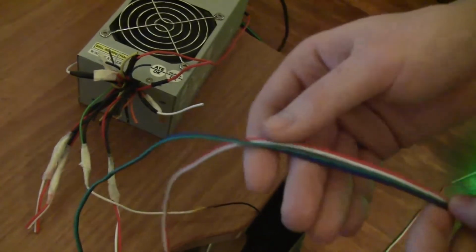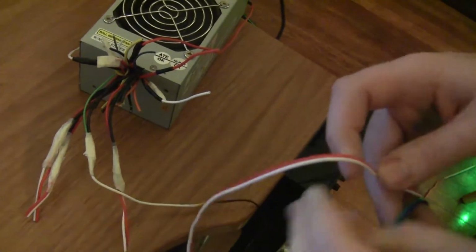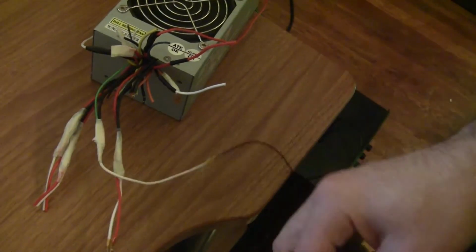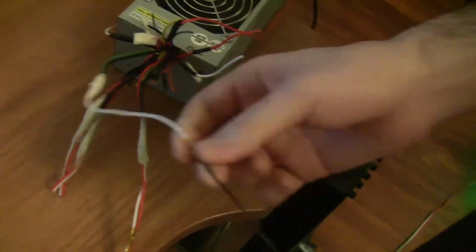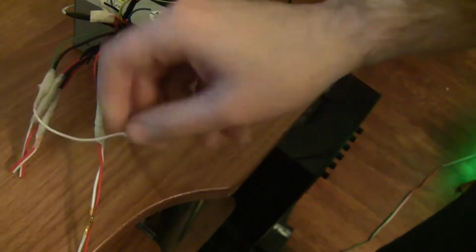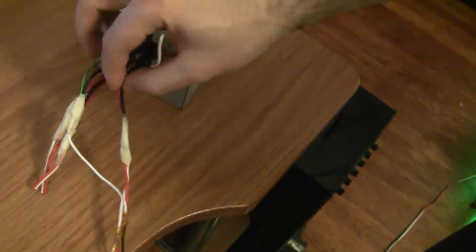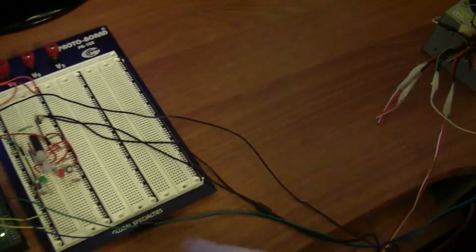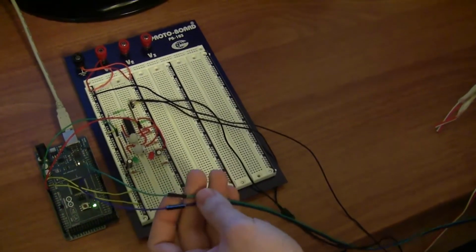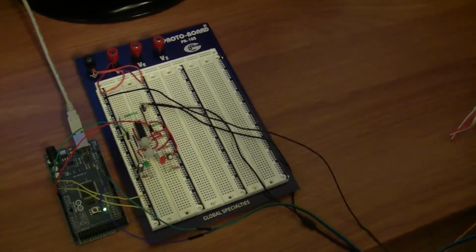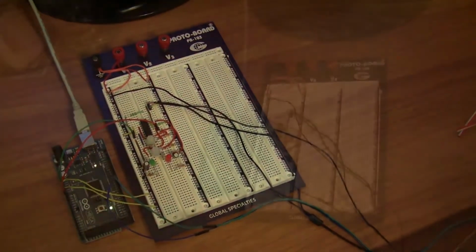So here we can actually see the 4 lines coming from our strip of LEDs. We have power and ground, which go directly to the power supply. We also have the ground from the power supply broken out so that we have a shared ground that's shared between the LEDs and also between the Arduino. And then in addition, we have these lines right here coming from the LEDs, which is our data and our clock, which is then fed to the Arduino, which Jeremy will now talk about.